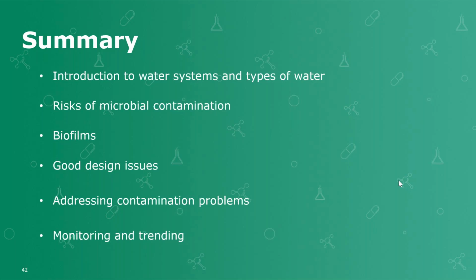And I think, just to recap something else I said, it's often the slowing down of water which presents one of the biggest problems. So where we've got a slowdown of the turbulent flow of water, non-ideal joints or welds, or sloping pipework with too much of a drop down, then these are all the kind of factors that can allow organisms to attach, and we develop these kind of niches of concern and so on.